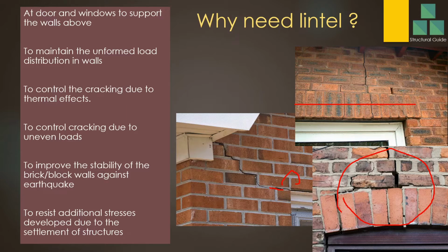One more thing to keep in mind: lintels control thermal cracking. In a normal structure, you have columns like this, and you also have beams like this. They are not straight, but think of them as straight. If you don't provide this lintel beam, there may be cracks like this. If you have a lintel, it controls the cracking. Therefore, lintels are very important in large structures, or where the area of the wall is large; you have to provide a stiffener column or stiffener beam. Those act like lintels.